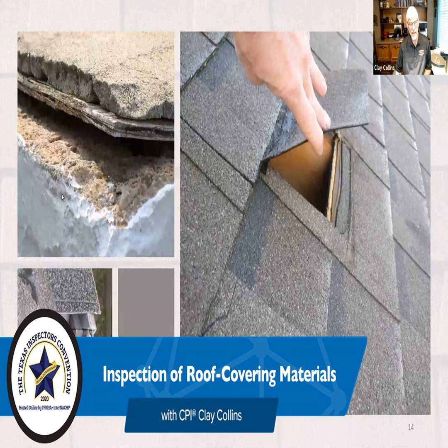about what might be missed, including, you see there at the ridge, you might have been able to see this with your binoculars, but you'd have only been able to see this area, and you would have to intuitively know that there were some shingles missing. And in this particular case, surprisingly enough, there was no evidence of moisture damage beneath that.